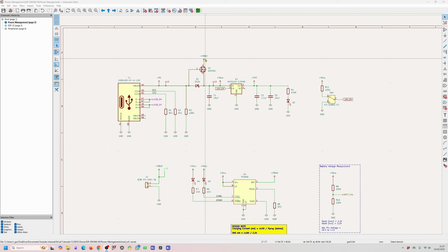Obviously, it may not be possible to meet the requirements everywhere, such as when you interface with an IC or something for a high current path. Those you can make strategic decisions to ignore, or add a non-DRC check there, basically.